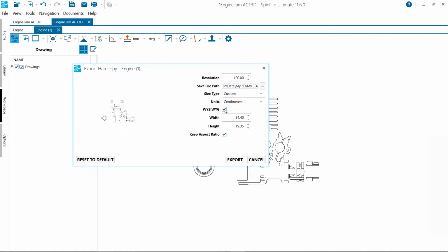What version are you running? So it's the resolution? Yeah, resolution. Okay. Have you tried increasing the resolution? The resolution's here, so you may go to 200 or 300 to see if that's better, because it depends on the size of the file, right? If it's a huge drawing or a small drawing, you may get the vectorization. That's the first thing I would try, the resolution.